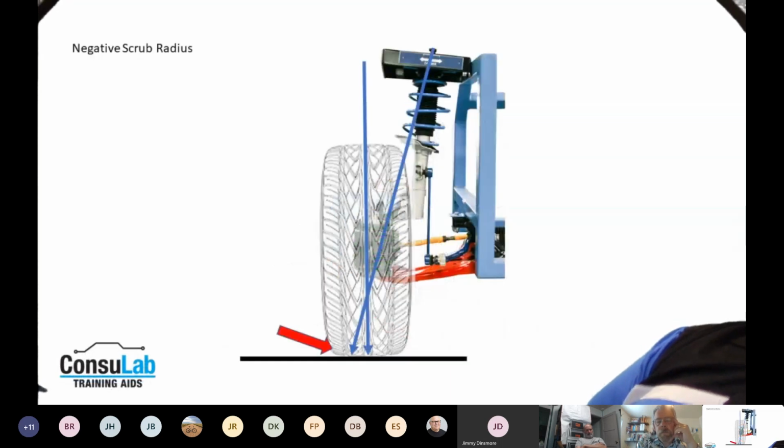When we go back into the strut, there are two places to adjust. We can adjust at the top of the strut. Moving the top of the strut in and out also changes SAI and camber, but the included angle stays the same, just like the spindle. And if the included angle is off, we could have a problem with a bent strut or something like that.